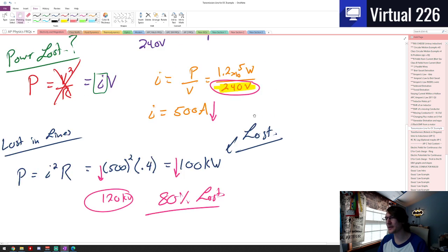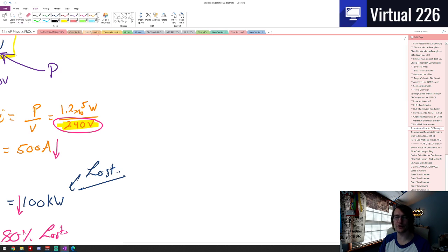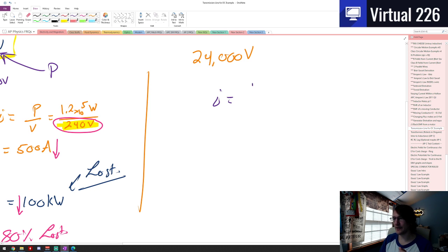I just need to say, hey, people, stop using 240 volts in your house. Let's use like 24,000 volts in your house. Because if we go through the same process again, the current I would have is 1.2 times 10 to the 5th watts divided by 24,000 volts.